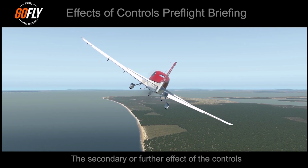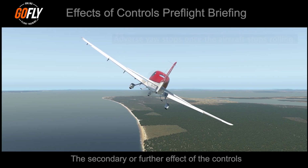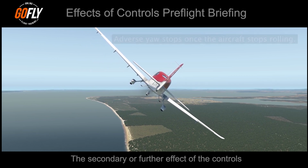Adverse yaw is caused by extra lift being produced by the upgoing wing, as when there is more lift, there is also more drag. This drag causes the aircraft to yaw in the opposite direction of the roll initially, then the yaw will stop once the bank angle is constant.